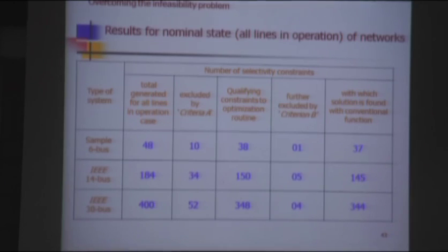And then recently, another concept known as adaptive protection is also being introduced. In adaptive protection, the fault currents are being monitored online according to the latest changing conditions. Then settings are calculated. That means the online settings are being calculated by, let us say, a mathematical optimization procedure, and at the same time these are being transferred. But it is not so easy.